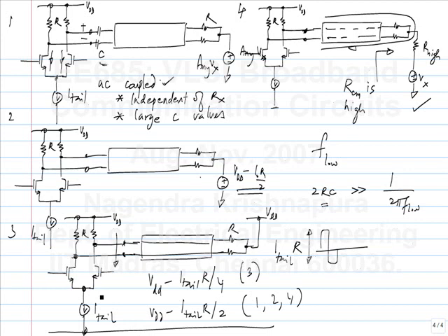Maybe it is not good from other points of view. Okay. So this gives you the highest common mode voltage, and all of them are driving the same swing. Of course it's important to keep that constant. If you have one transmitter driving 1 volt, and another driving 2 volts, it is more difficult to design the 2 volt transmitter. But that's not what we are talking about. Here we are talking about 4 transmitters, all of which can drive, let's say, 1 volt peak to peak. But one of them has a higher common mode voltage than the others. So that is easier to design, isn't it? Is that convincing, or does it need more explanation?